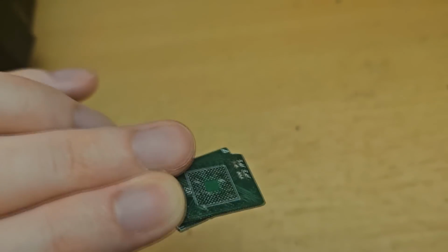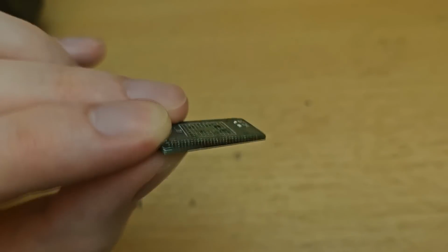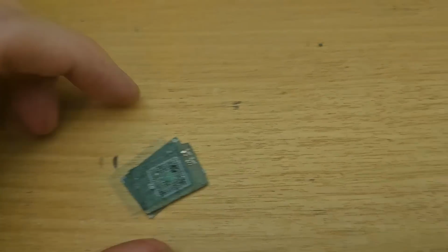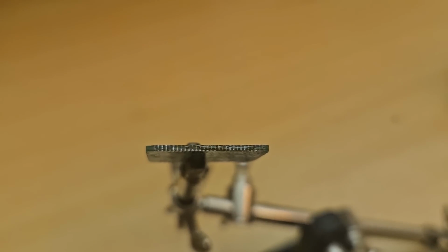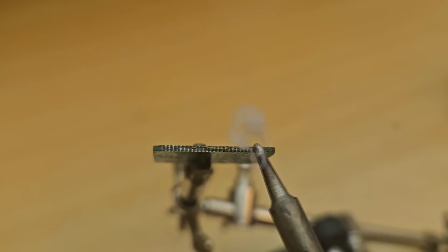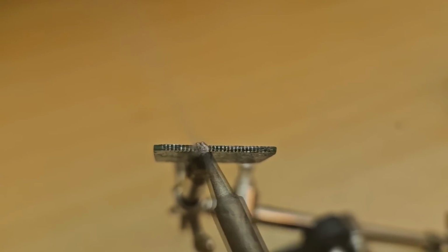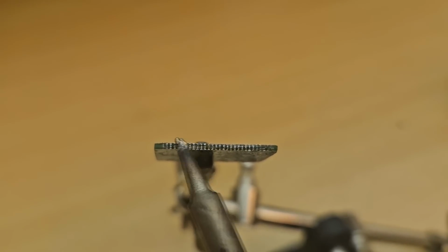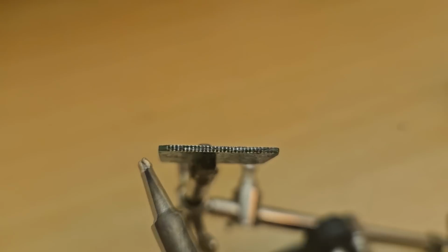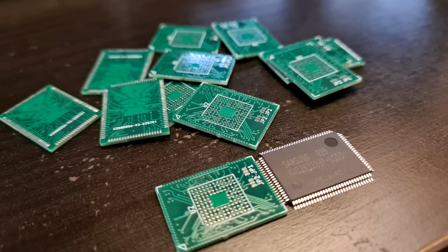So since they cannot mass produce these castellated holes, I decided to do them manually. Here's a look at the PCB that's been sanded down. The edges I have soldered to. That's why it's silvery rather than coppery. The edges are not particularly solderable. I made a mistake here by allowing the solder mask to go down these vias, whereas I should have excluded that, and then we would have a cleaner edge. But that's okay, it didn't present any problems. Here's a PCB before sanding. So you can see on the edge there are no connections, only on the bottom.